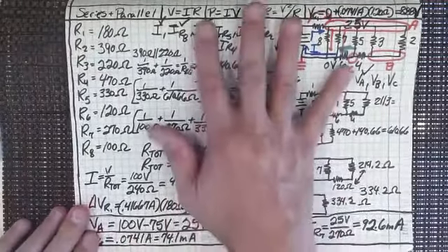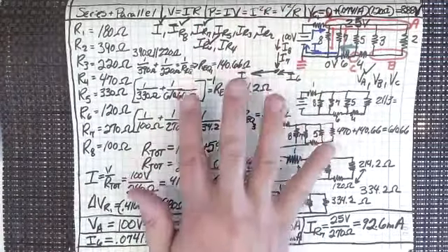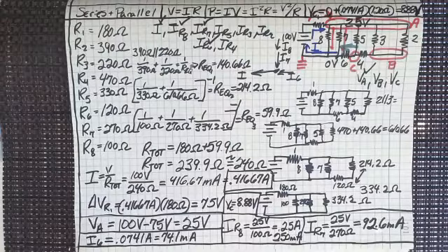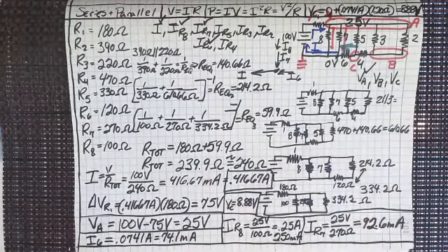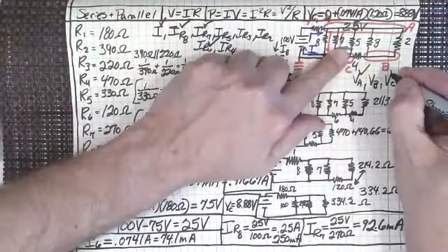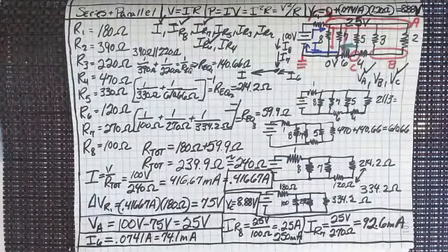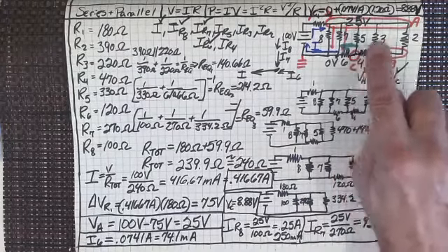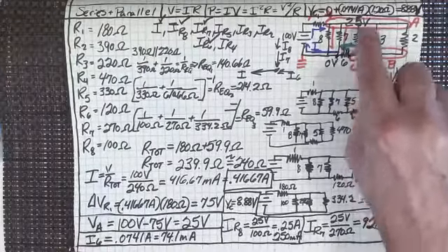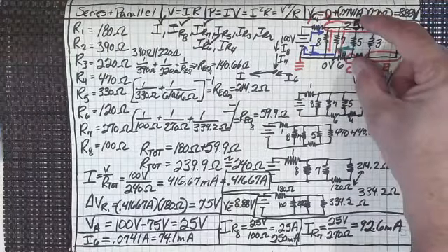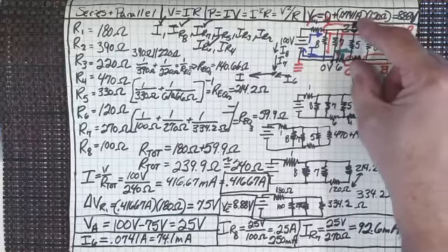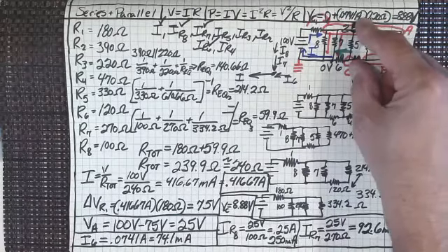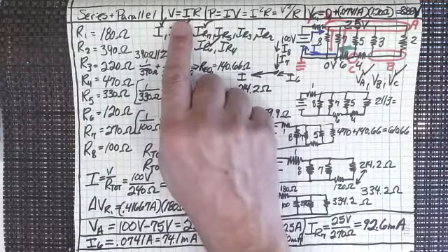We've still got to finish what it is that we're trying to accomplish. We still need, oops, I forgot to mark off V sub C, our last thing that we did there. What else have we got? Yeah, we don't have 5, 4, 3, or 2. But 5 isn't very far away, is it? Because we now know what the voltage at C is. We know 25 minus 8.88 is the voltage drop across number 5. So that should be very easy to figure out what the current through it is, right? Ohm's law, V equals IR.